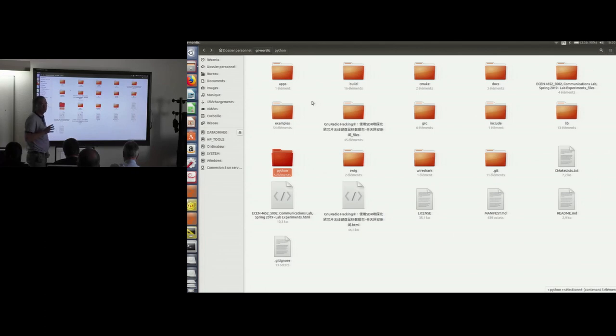I suppose that you know these subdirectories. The first one is lib, where you find all the C++ blocks, and include has all the headers related to these blocks. GRC is the directory where you find the XML files that GNU Radio Companion will use to draw the blocks with the inputs and outputs.